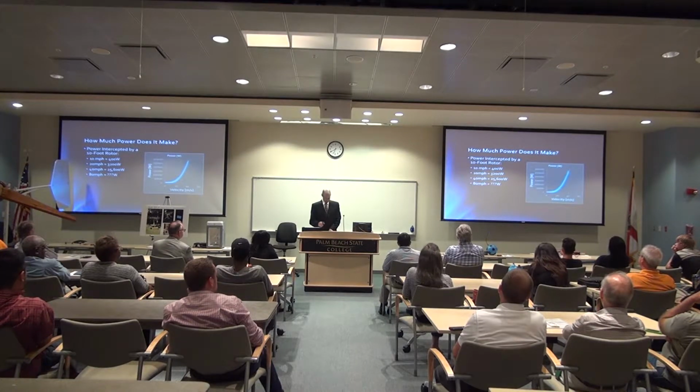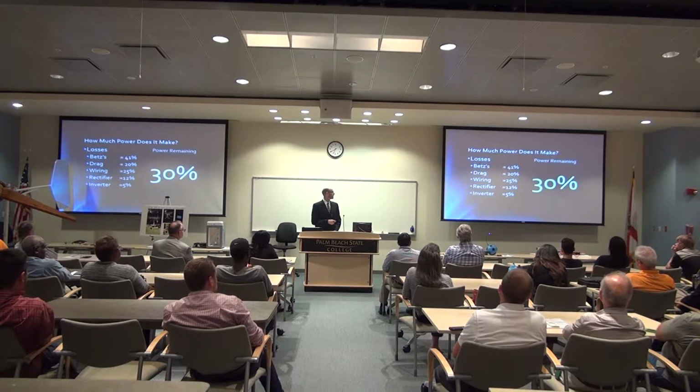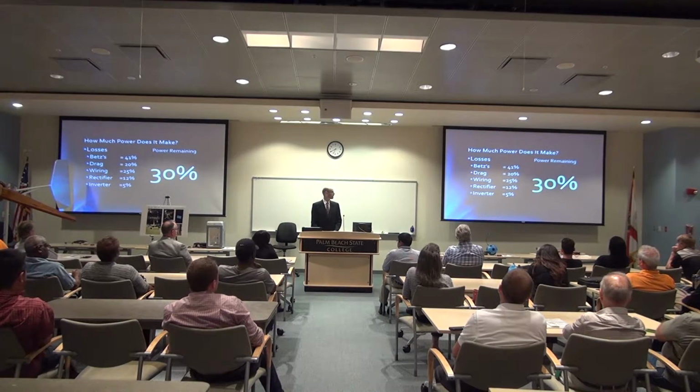In so many places in life, there are losses and limits. So what kind of losses does our turbine experience? Well, right off the bat, we're going to lose about 20% to friction in the bearings and drag. We'll lose about 25% in the wiring of the system.